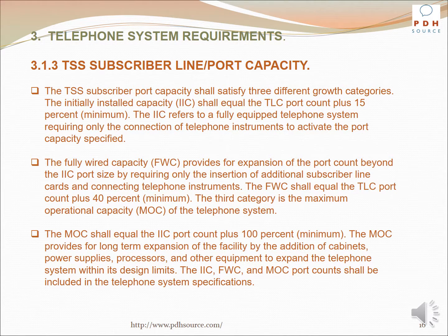The TSS subscriber port capacity shall satisfy three different growth categories. The initially installed capacity, IIC, shall equal the TLC port count plus 15% minimum. The IIC refers to a fully equipped telephone system requiring only the connection of telephone instruments to activate the port